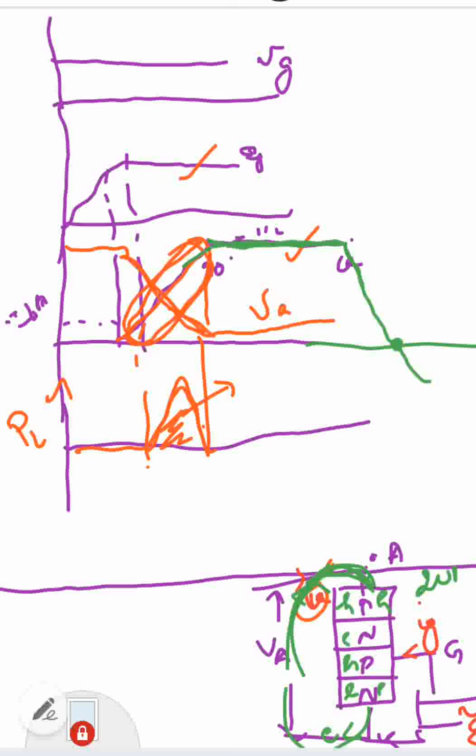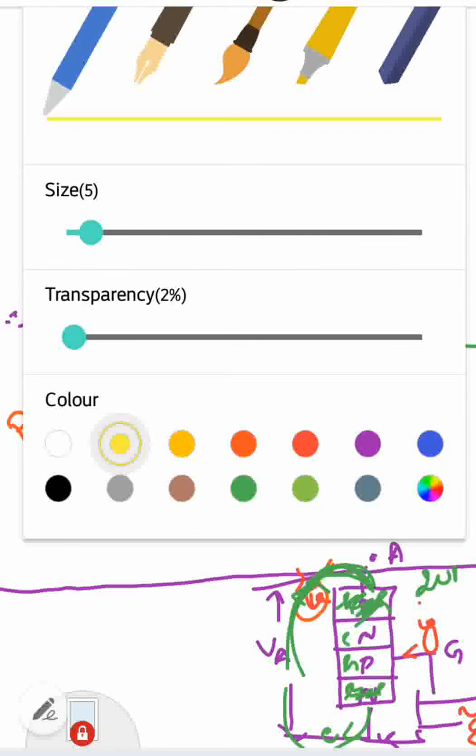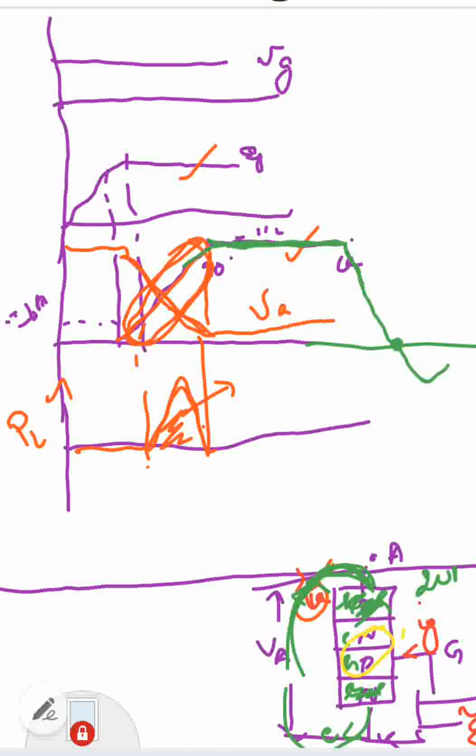So the 90% of the charge carriers is removed from the outer layers after some time. Now there are some still trapped charge carriers inside this layer, junction J2, which can be removed only by using recombination. Okay, so I'm once again drawing the anode voltage. The same graph I am drawing here. The anode voltage slowly decreases and finally it has reached to that value, and the anode voltage stays here.